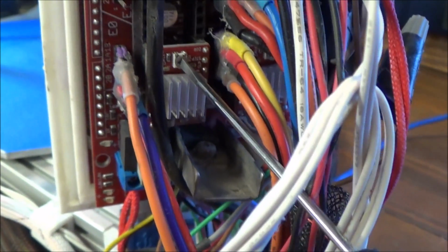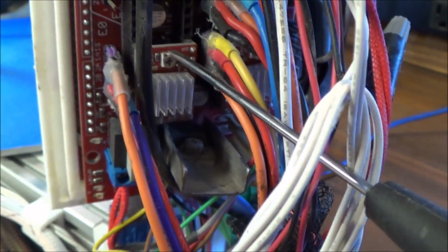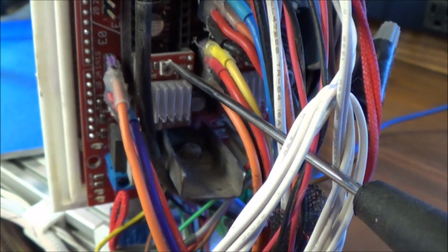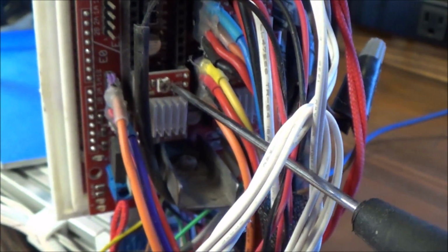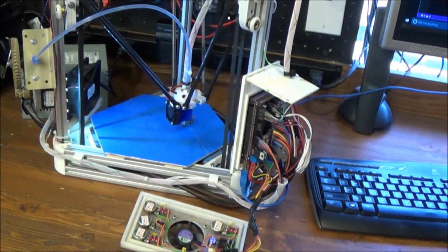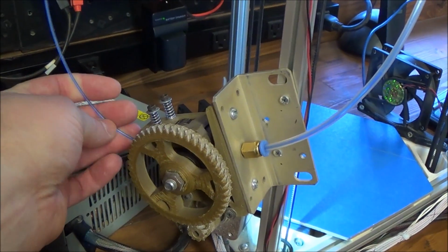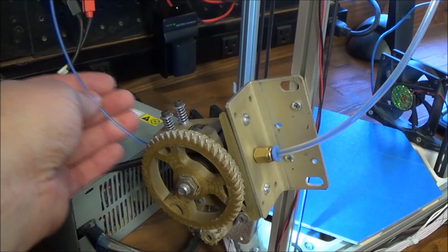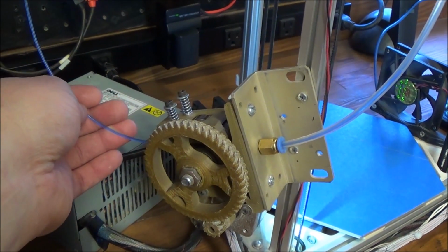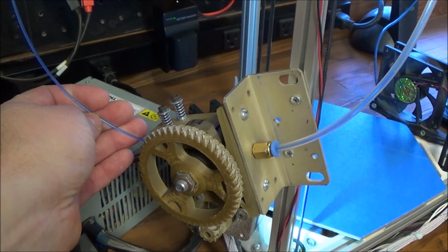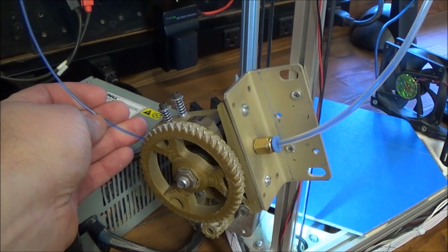Before you start, there's a potentiometer on these stepper motors. Go ahead and set it to the middle. There's a flat piece on the top of this pot, meaning that it's pointed straight down. That's right in the middle. So crank them up later if you need more power for your stepper motors. A little tip, this filament is kind of translucent. I suggest you use a solid color for calibrating. I wasted a lot of time one time because the transparent filament can be a little harder to use.